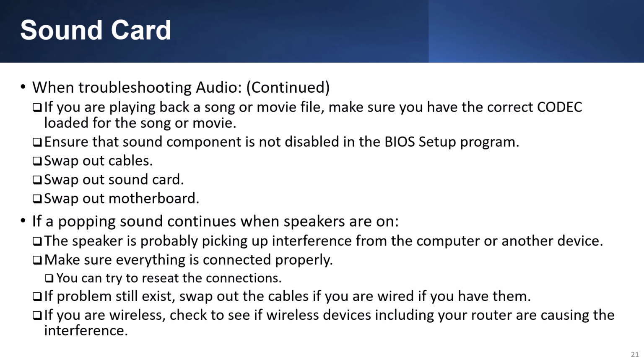If a popping sound continues when the speakers are on, the speaker is probably picking up interference from the computer or another device. Make sure everything is connected properly and try to reseat the connections. If the problem still exists, swap out the cables if you're wired. If you're wireless, check to see if wireless devices, including your router, are causing the interference.